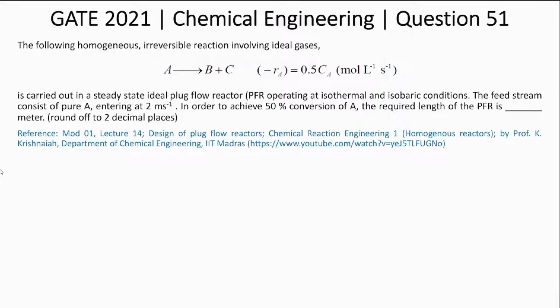And we deal with that by using the term epsilon. Okay. So given it is a gas phase reaction, that means it is a variable volume system. So we can find epsilon like this. We take our reaction A gives B plus C and we just write down the moles of it. So 1 mole of A will give 1 mole of B and 1 mole of C.